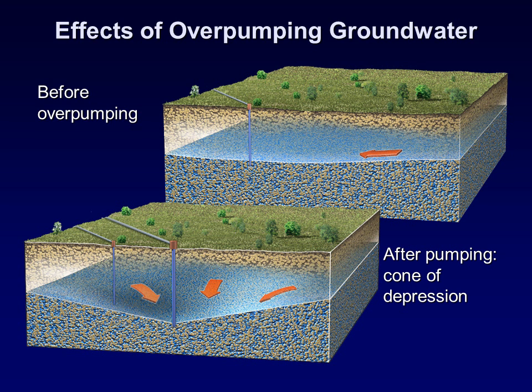In the second image, larger wells, or just this one larger well, causes a cone of depression in the water table, changing the direction of the flow. Okay, so you can think of this like a milkshake. If you're drinking your milkshake from a straw, it's going to create a little cone of depression there. It's going to sink in around the straw because you're drawing it out faster than it can naturally flow back down to the bottom of the straw, or in this case, to the bottom of this larger well.